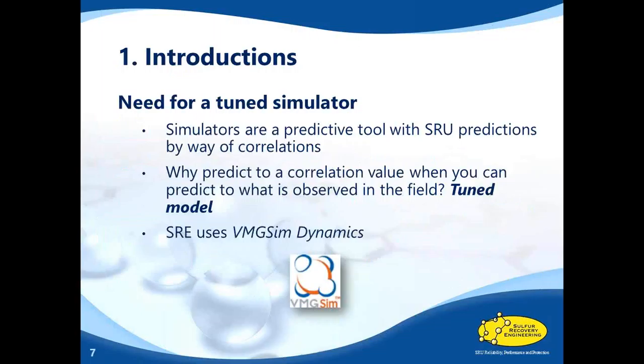But what's the next step after that? How can you change? When you're trying to predict, for example, your SRU tail gas composition, you've got a 3-stage, you've got your thermal stage doing a correlation, and your first, second, and third stages are all doing correlations. Hence, when you're trying to predict what your SO2 emissions are, wouldn't it be better to have your model produce the results that you observed in the field?